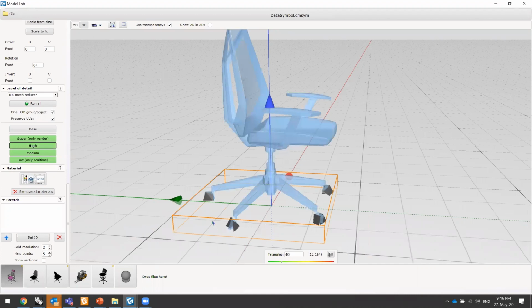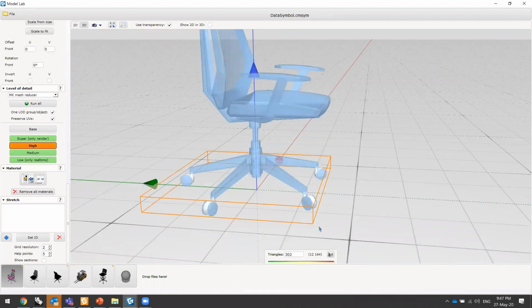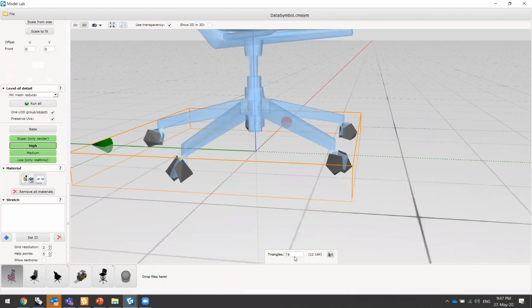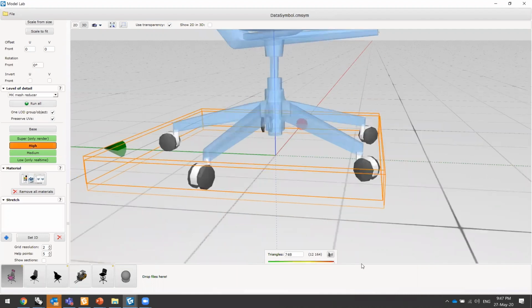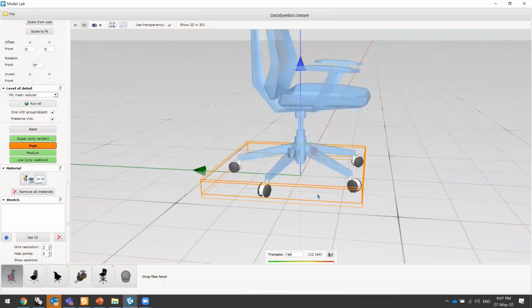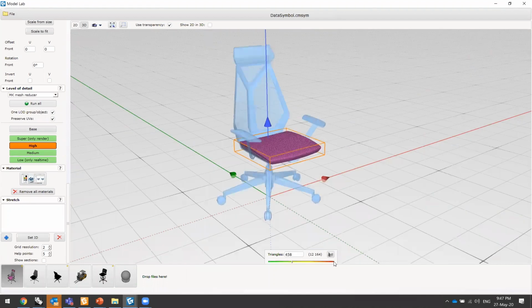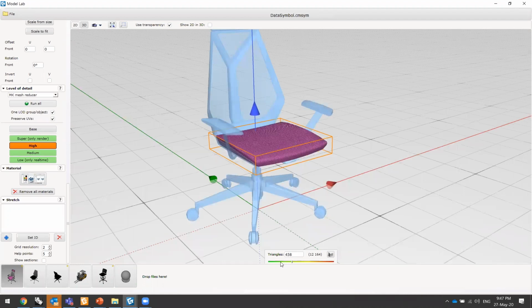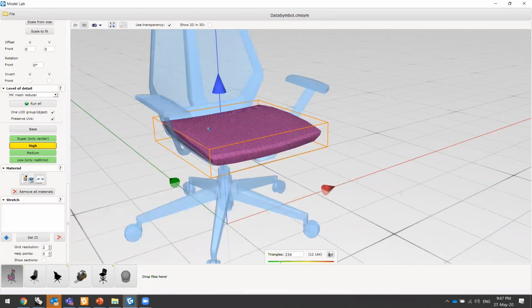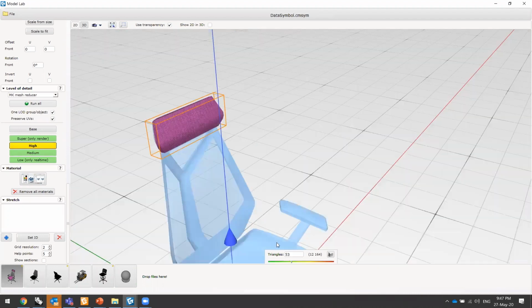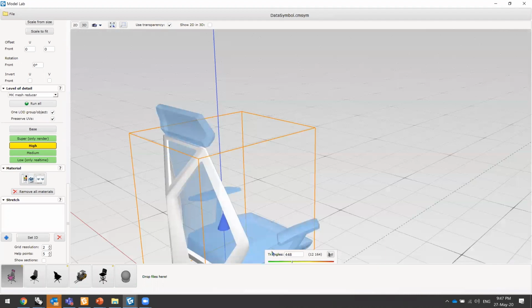So slide it up. You want this, slide it up all the way. And let's see. Oh, I forgot to, let's do that again. Let's take this, it's 128 triangles, slide it all the way up. I added about 700. So let's see where I can take away 700. So this was 2003. I mean, for high, it's much lower, but still, I can kind of reduce it. And now I'm in yellow. So let's take this one. That's pretty low already. Perhaps this one, let's do 200.